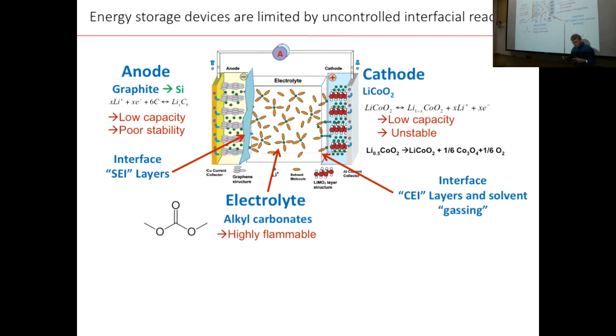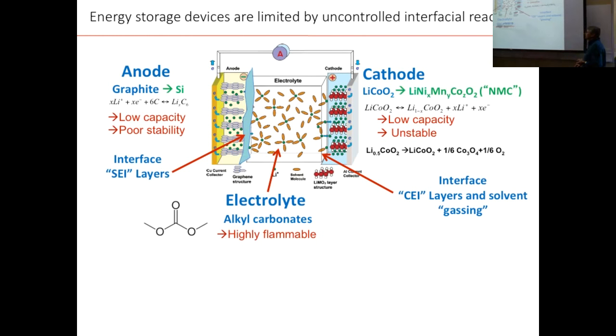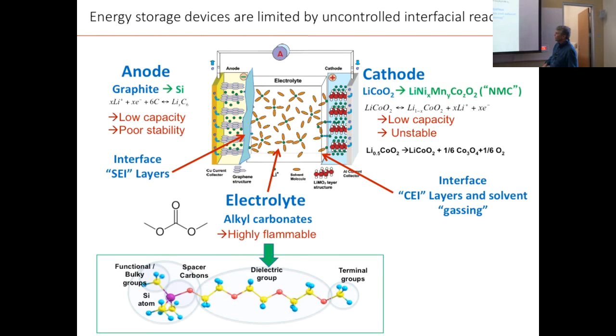The battery packs are basically like aluminized baggies is the best way of describing it. You have an anode and a cathode with the electrolyte in between, and it's sandwiched together into an aluminized, flexible plastic bag that then begins to bow out if you degrade the electrolyte and start producing CO2. Now, you might think that would be good, making the CO2 as being like a fire extinguisher, right? But it turns out that that is bad because now your battery actually has pressure buildup on the inside, and that pressure buildup can create lots of problems downstream that are not particularly good.